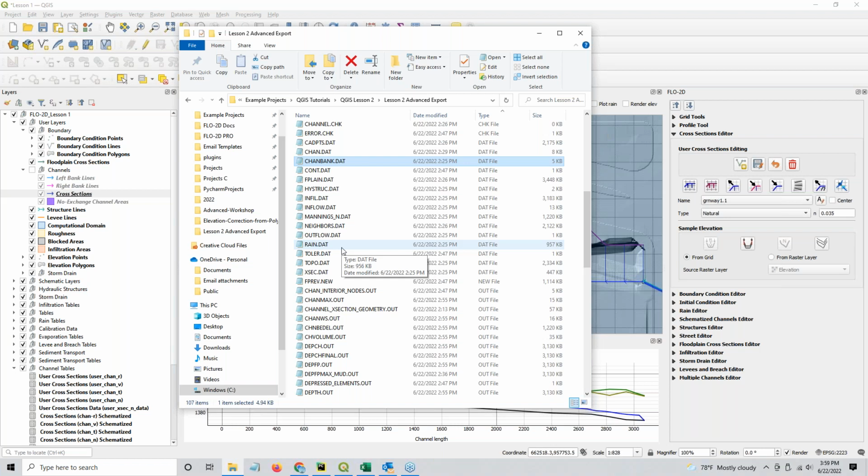So sometimes when you fix one, like increase the end value, or change the slope a little bit, or change the length a little bit, anytime you do something like that, you're just going to push the error, or push the time step decrement, somewhere else in a channel. So unless it's really bad, or there's actually something wrong with the grid element that's causing the channel to slow down, just leave it alone.